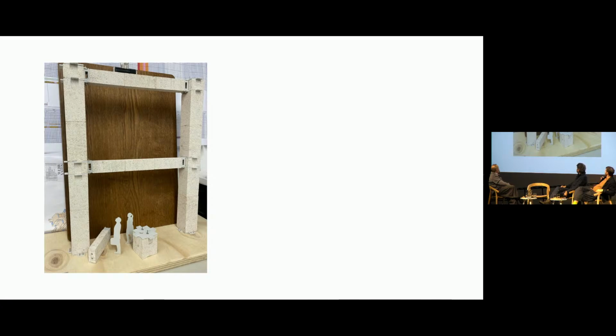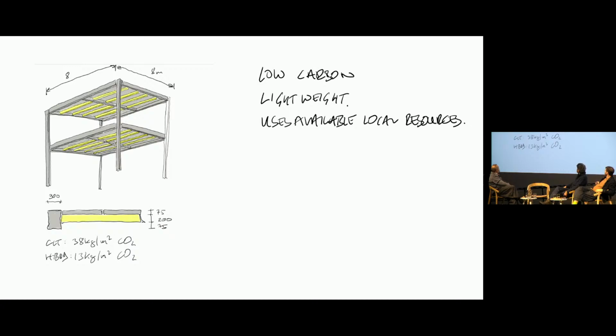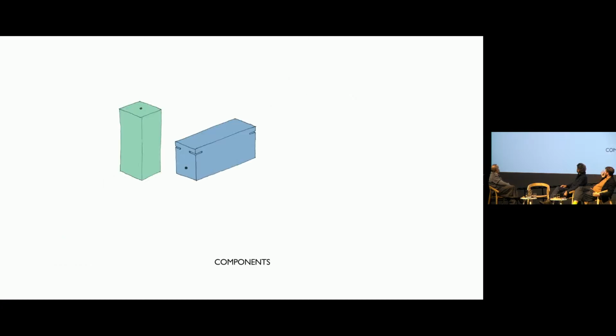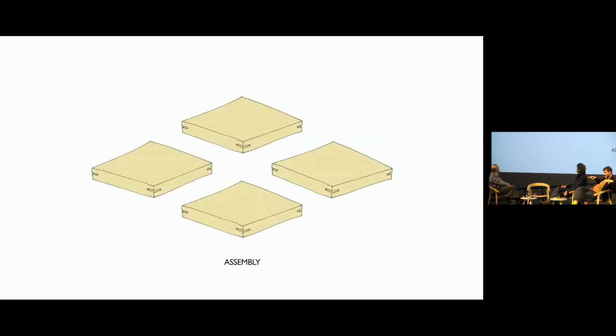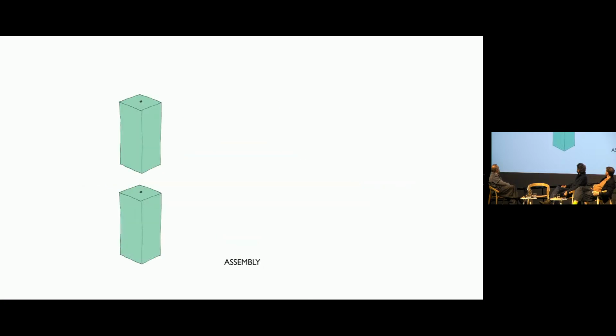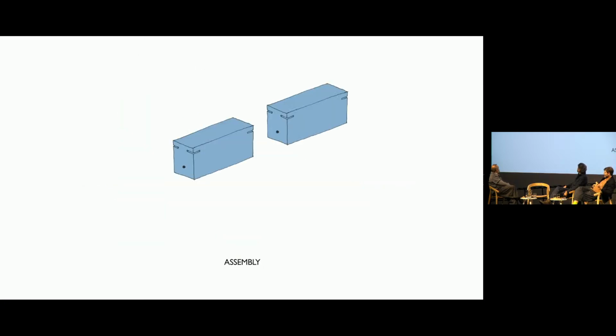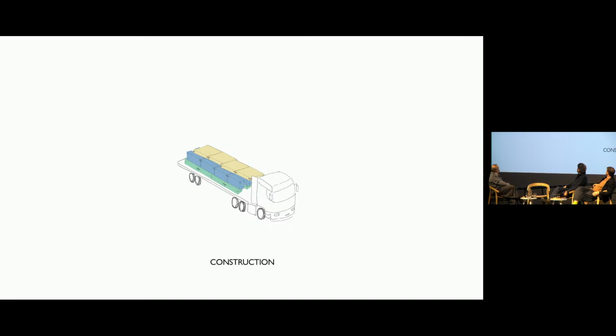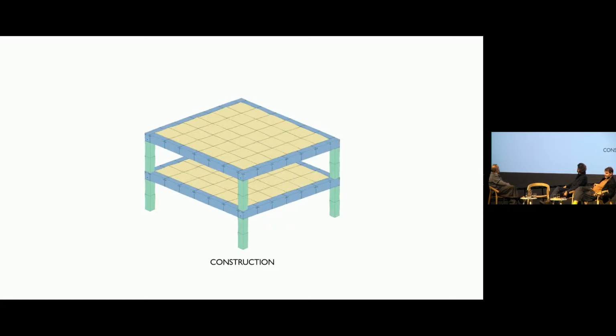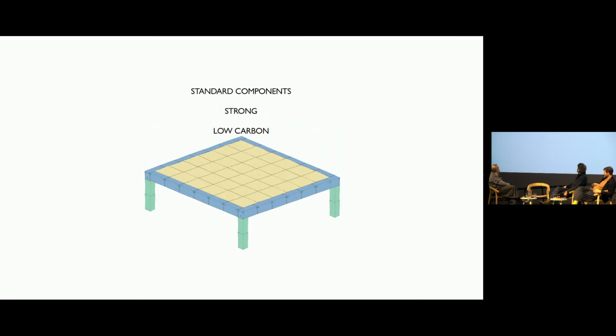So if it's like steel, you make a stick system and you bolt it together with bolted connections. So it's literally like you're building a steel building with steel beams. Is it this kind of system where we have the long span beams and the composite timber and stone in between? The torsional floor plates from the tile puzzle, we can make big floors with this without any kind of reinforcement. So we had the idea that we could make a post-tension stone column and beam system and put the floor tile system in between it and build actually readily upcyclable buildings quite quickly without formwork and falsework, very low carbon.